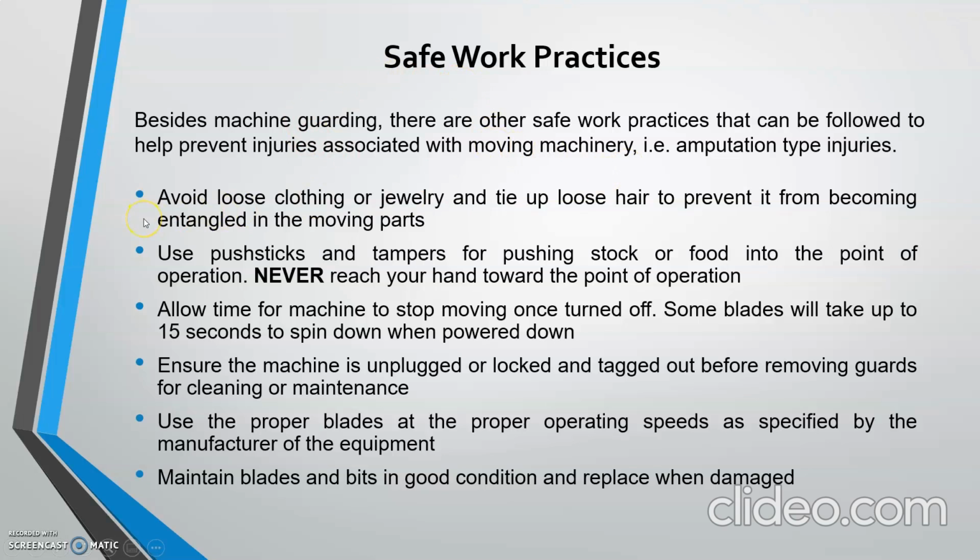Okay, first, avoid loose clothing or jewelry and tie up loose hair to prevent it from becoming entangled in the moving parts. And then use push stick and tamper for pushing stock or food into the point of operations. Never reach your hands toward the point of operations. The third one is allow time for machine to stop moving once it is turned off, because some blades will take up to about 50 seconds to spin down when power is down.